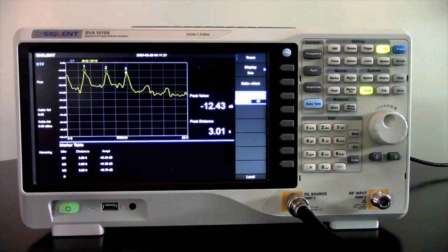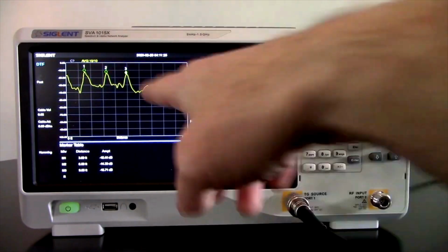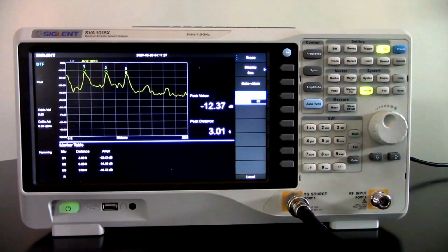As the connections may degrade over time, we can compare the new picture to this existing picture. So as your cables age, you can start to compare, is it corroding in certain areas? I have had some customers report that they've had lightning suppression elements on their cable start to wear through the dielectric, and they can see that using the distance to fault feature. So again, they can check out where that exact break is or where the problem is before they even get up on a ladder or climb the tower.